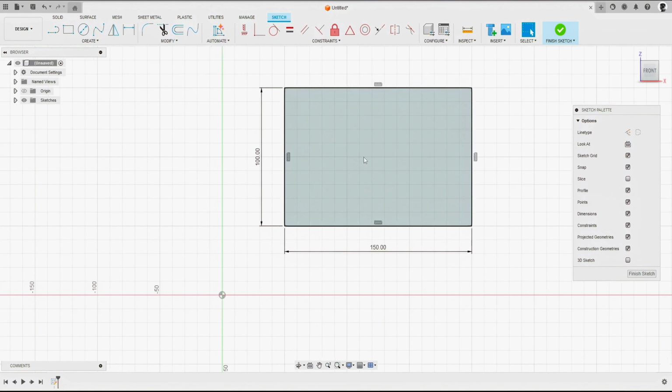And last, we'll go for the two distance chamfer. So here, we're going to select two lines or a corner point. Let's go for the corner point. Then first of all, we need to enter in the highlighted arrow. So in this case, the horizontal. Let's go for 50 mil there. And then let's select this arrow here. And let's go for, say, 15 mil. Press enter. Now we've got those two linear distances there.